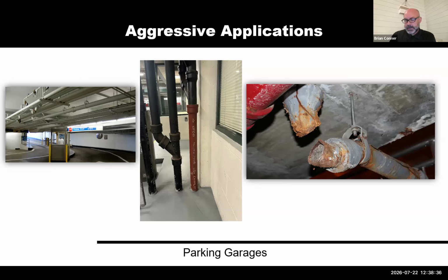So, one thing that makes Charlotte Pipe a little bit different from the others who are making these enhanced coatings is that we e-coat both the inside diameter and the exterior, the outside diameter of the pipe. So, it's electrostatically charged ions. We charge positively the pipe and fittings, and we negatively charge the coatings so that they electrostatically adhere to the substrate, which gives a superior bond to both pipe and fittings.